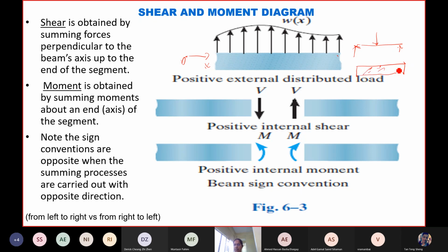After the shear force diagram, for the bending moment also, you will start from one end. If you want to draw the bending moment, if it is simply supported, it should be 0 here, right? It will be 0 here. For a point load, it will be a triangular shape, something like this, isn't it?